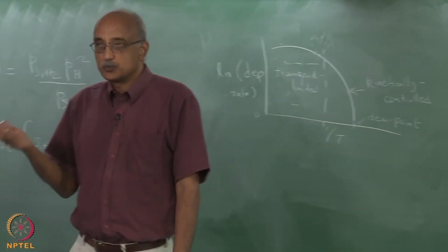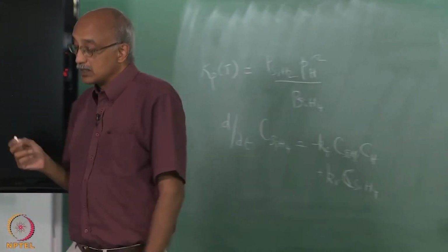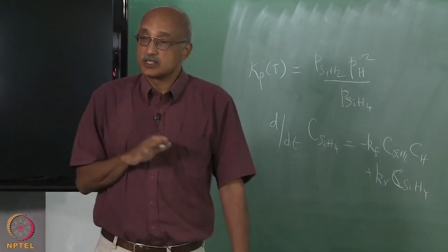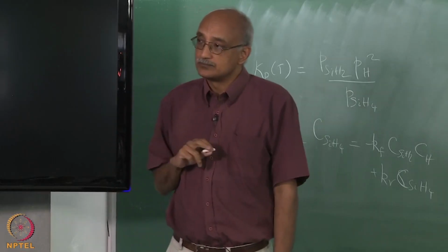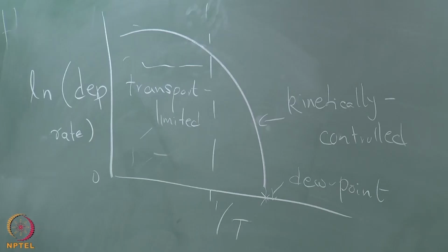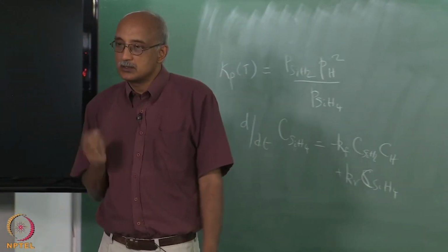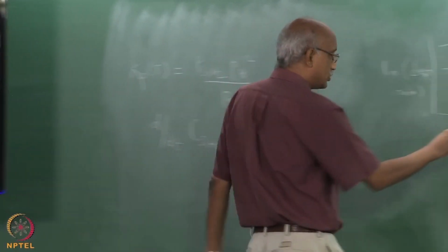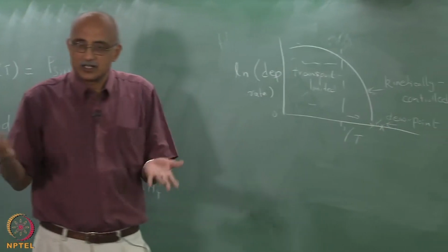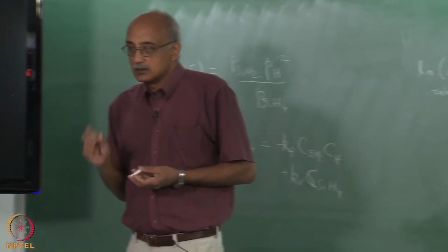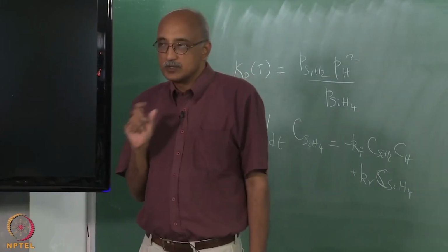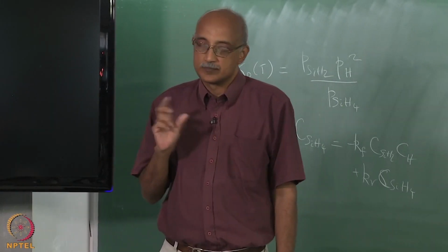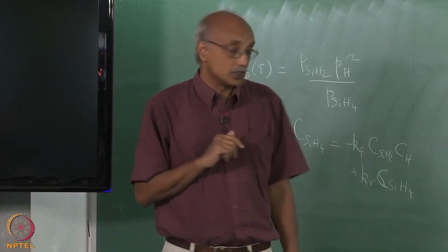Of course, you are all familiar with dew point in the case of water condensing and so on, but one thing that is unique about dew points in CVD systems is that they are not unique. In other words, depending on whether you approach the dew point in this direction or in this direction, the dew point may be different. So, we will talk about that again in more detail, because that is a very, very crucial thing to understand in CVD reactors. And in fact, the behavior of the film between the two dew points, it is like a hysteresis effect very simply, but when the temperature is between these two dew points, the film has some very, very interesting characteristics that can be exploited for certain applications.